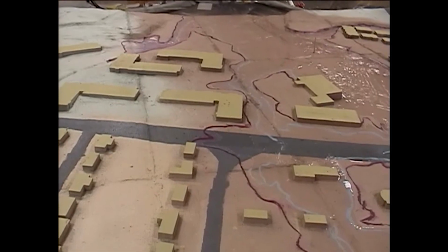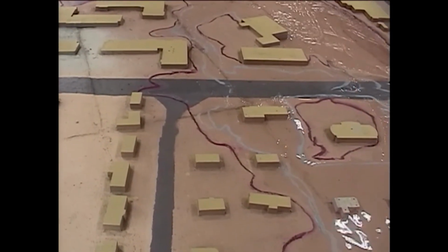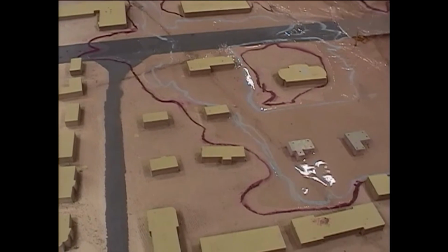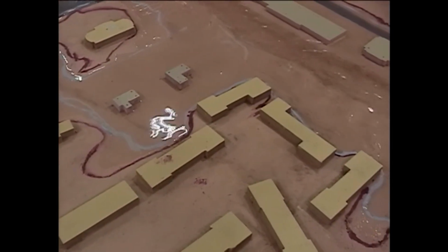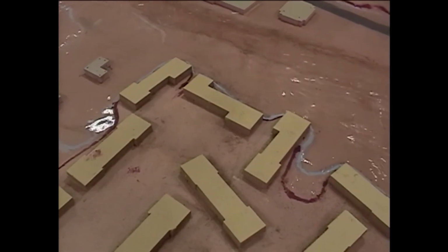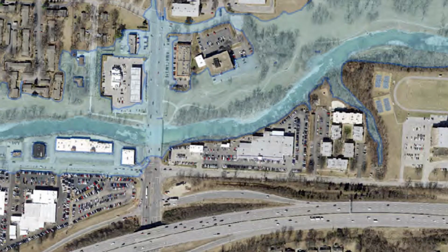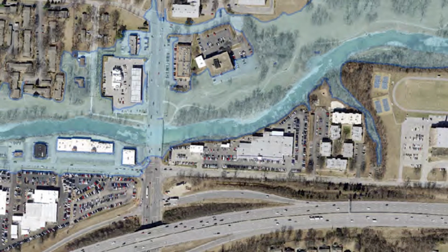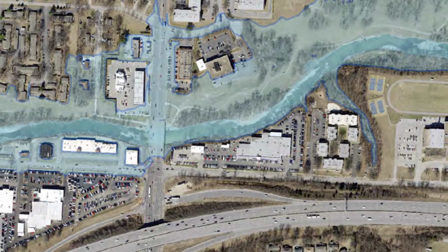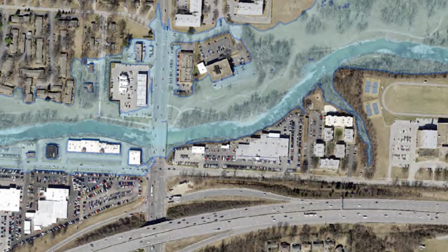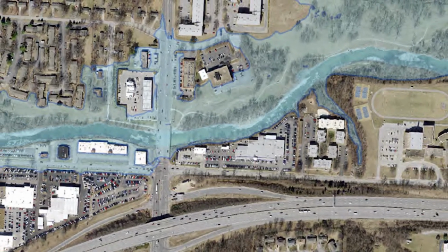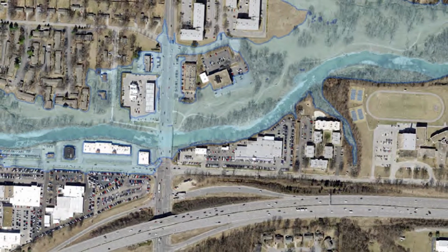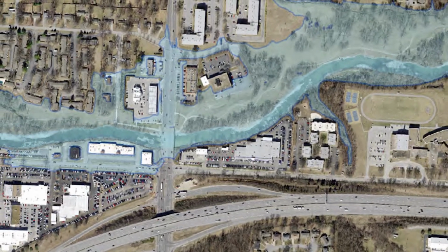And similar to the physical model, it went through a shakedown test as well. Once it was up and going, we ran it to make sure that it ran, and then got some initial results. So now is when we start comparing those with the physical model, looking at observed flow patterns and observed water elevations and velocities. We actually did take measurements of velocities in our physical model using a pitot tube. And then going back to the computer model and seeing what differences there are, and then trying to explain why.